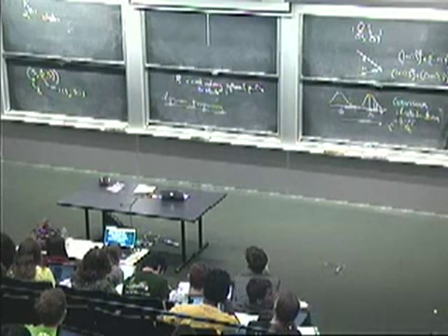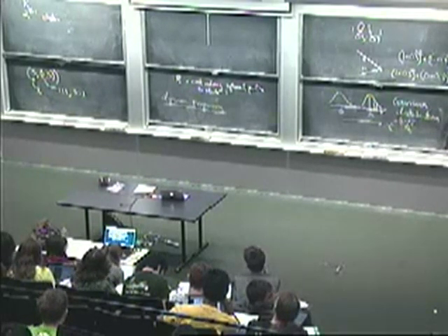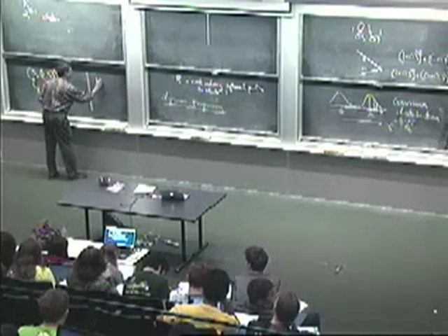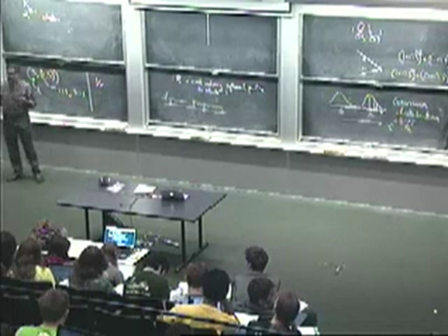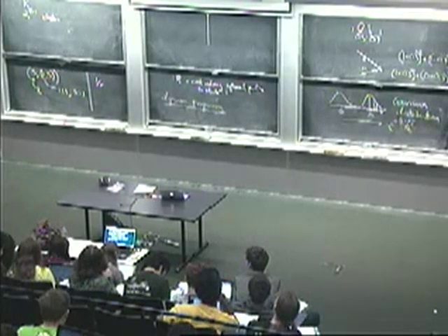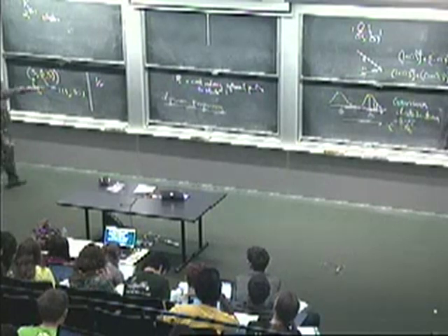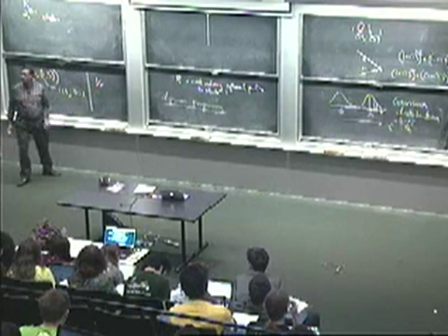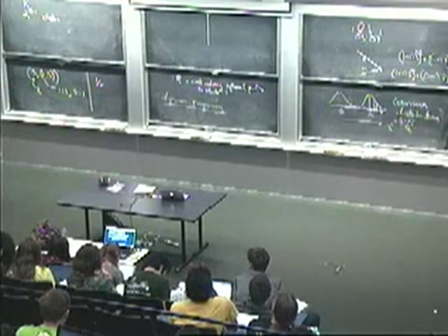It's 1/2, right? The rate is 1 over the number of parity bits you're generating per message bit, so a rate of 1 over r. So these are rate 1/2 codes, just like the rectangular case.